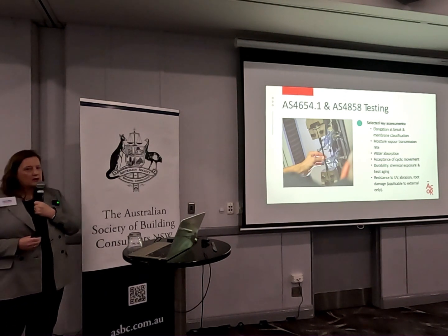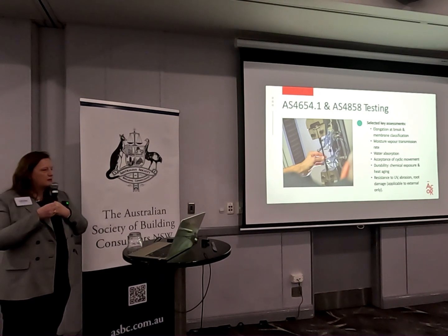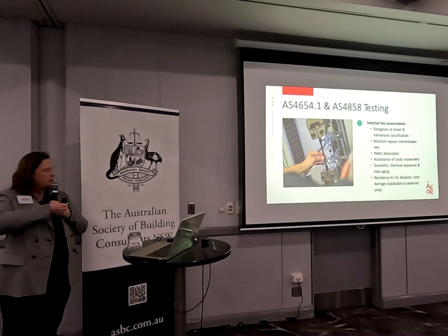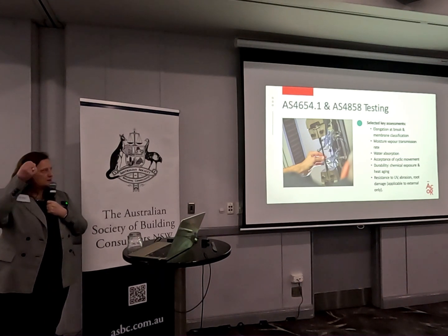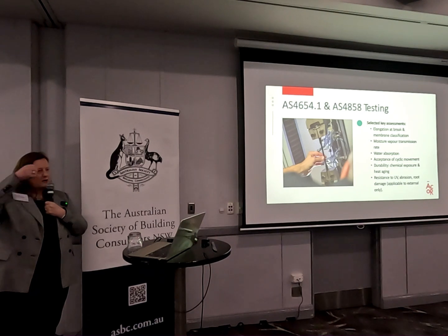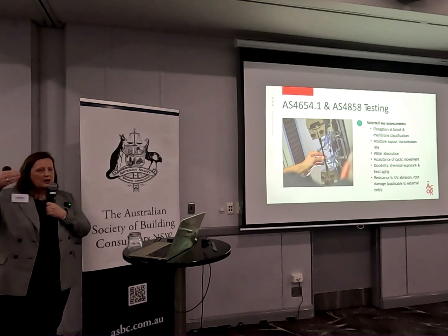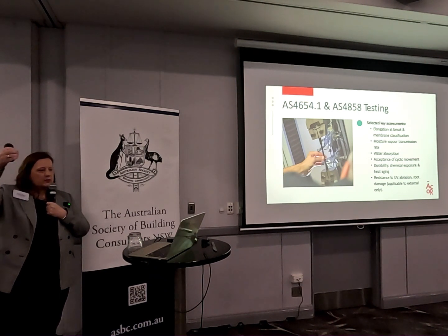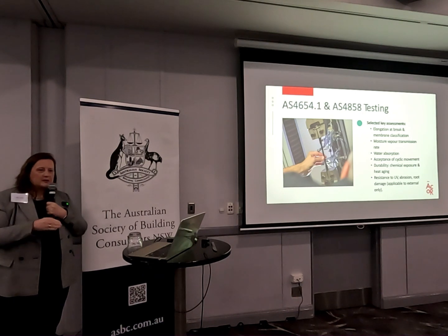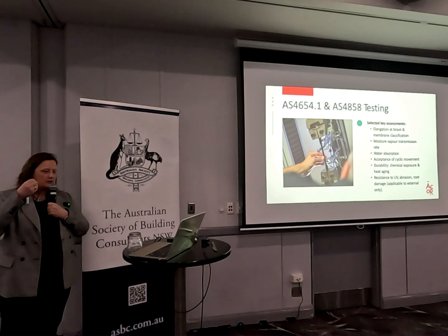You may have heard of different classes of membranes. To determine that class, they put a dry sample of the membrane under elongation or tensile testing. Depending on how far it stretches before it breaks, that will determine the class. So class 1 has the most extension, greater than 300%, and has the most flexibility. And then you go down to the class with the least flexibility. It will break much sooner when you put it under tensile load.